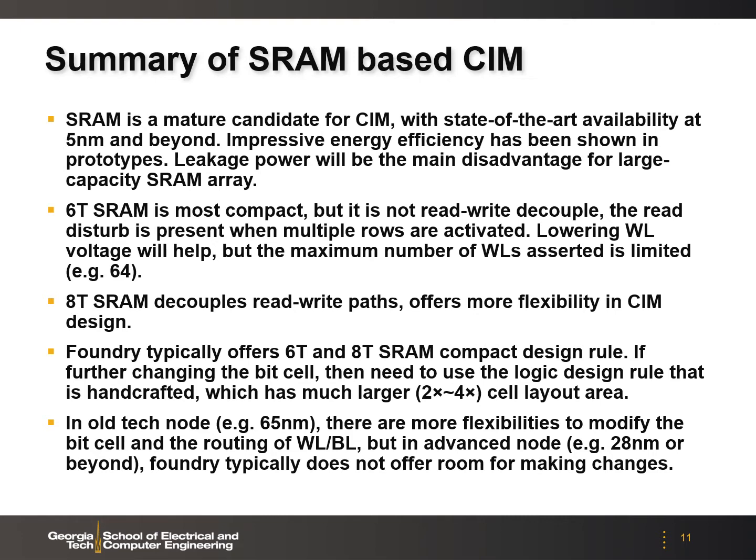Foundries typically offer 6T or 8T SRAM compact design rules, but if we want to further change the bit cell to add more routing, bit lines, word lines, then we need to use the logic design rule that is handcrafted, which will have much larger cell layouts.